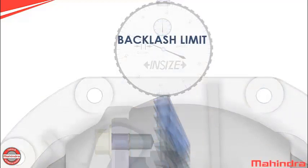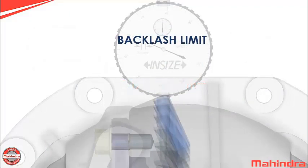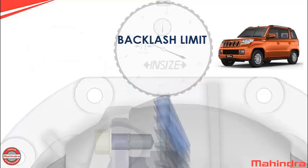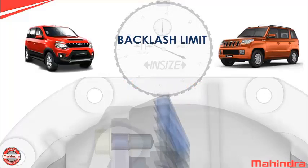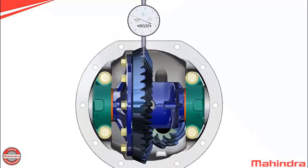Remember, the backlash limit is, for Xylo and Conto, 0.12 to 0.20 mm and for TUV300 and Neosport, 0.08 to 0.15 mm. If it is within our specified limit, then the assembly is okay and ready to use.